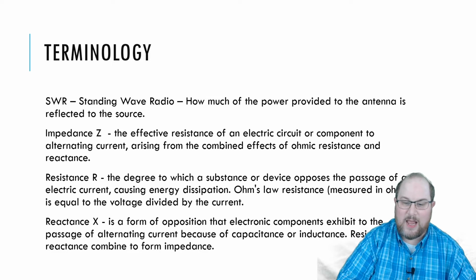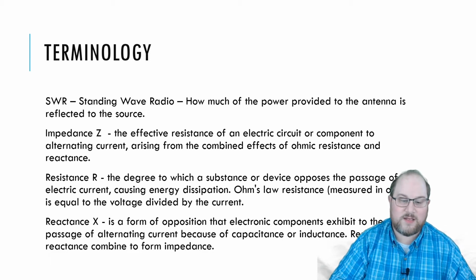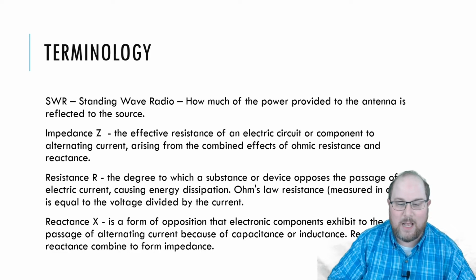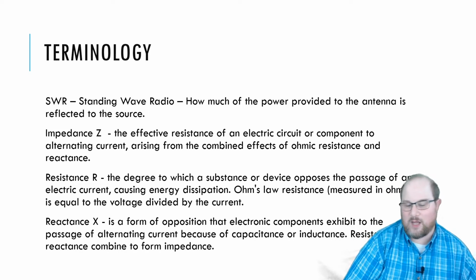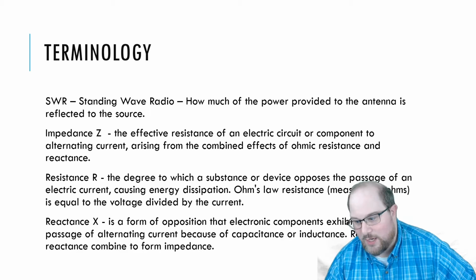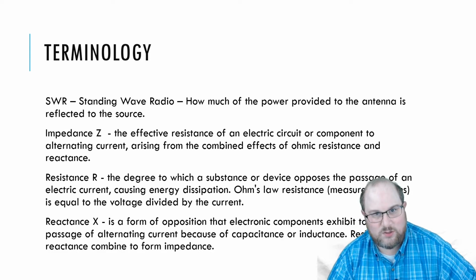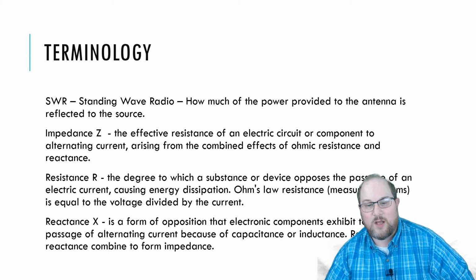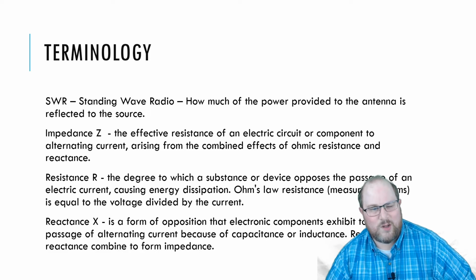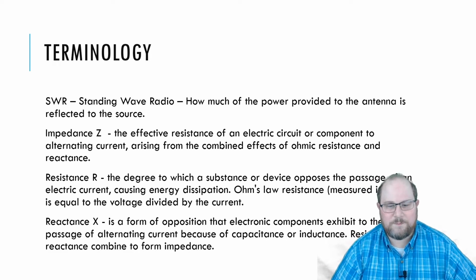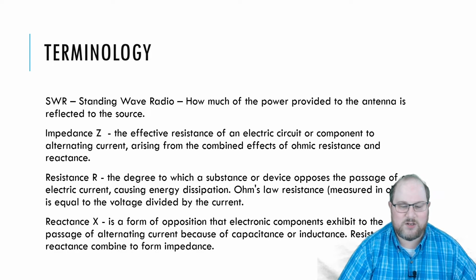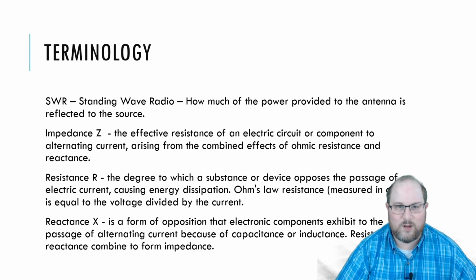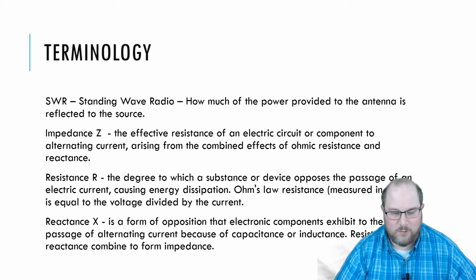Standing wave ratio. How much of the power provided to the antenna is reflected to the source? So how much power you're getting back from the antenna to the radio. If the SWR is too high, it could definitely damage your radio. Typically, you want to have as close to a 1-to-1 ratio as possible, no more than 2-to-1, 3-to-1. A lot of the inexpensive built-in antenna tuners cannot handle more than 3-to-1 SWR on your radio.